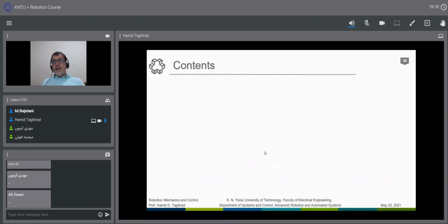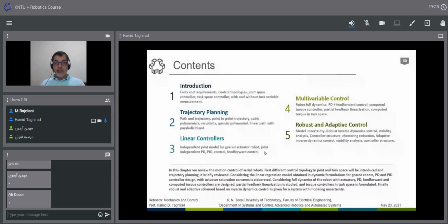By this means, we can conclude the linear controllers. Of course, there are more, but I just name some of them and summarize. What we have given in this part is a simple PD controller. Then we add an integrator to it to take care of the steady state error. And we saw that the integrator part of the PID is somehow giving some lag to the system.